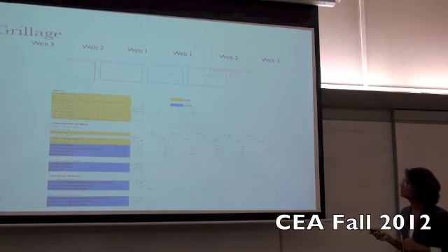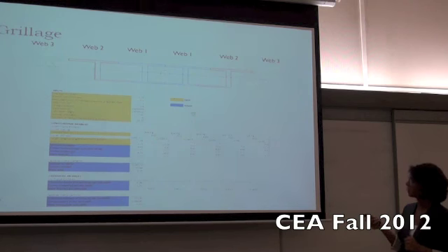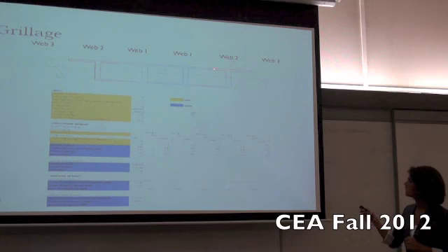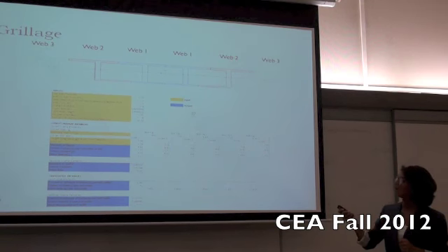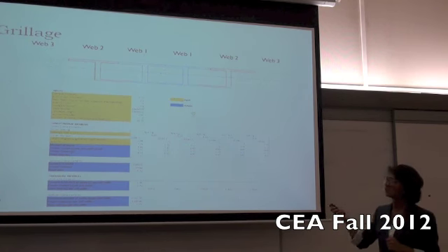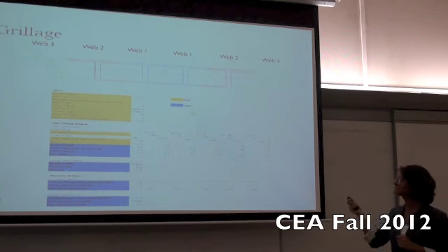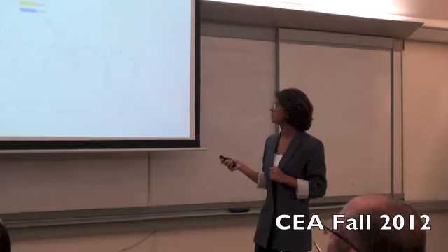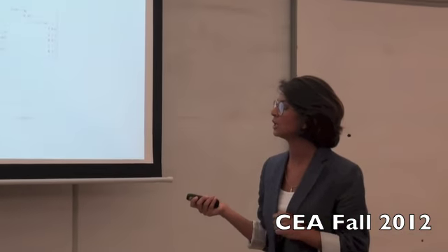For our grillage, we have this cross section, and we divide it into 6 I-beams. We make it this irregular shape in order to allow the centroid to coincide with the y-axis of the neutral axis of the whole cross section. And we make an Excel sheet to calculate the general properties that we will use in SAP 2000.